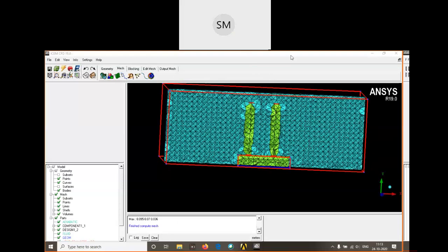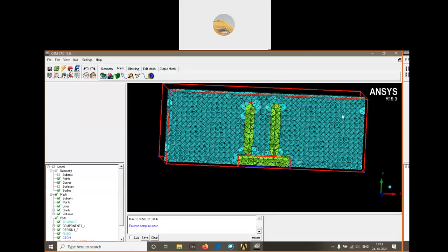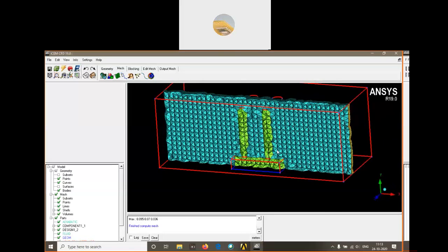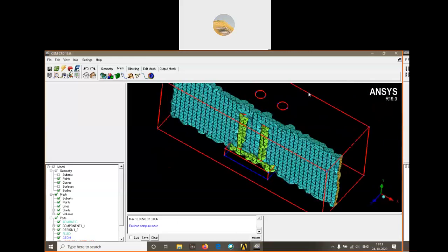No, it's a bad mesh. Okay. Why I'm telling it's a bad mesh is it failed to capture my geometry. A good mesh will capture your geometry clearly. See, your cylinder is not looking like a cylinder. It looks like something distorted. So this mesh cannot be used to perform a good CFD simulation. But this is our initial mesh.